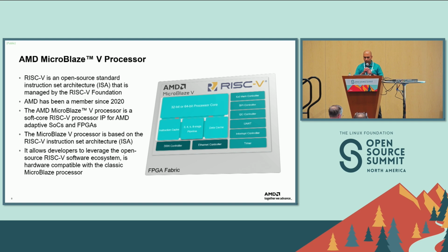So I'm going to talk about the MicroBlaze-V hardware a little bit here. MicroBlaze-V is a RISC-V version of the AMD MicroBlaze soft processor. It is available in most of the AMD devices supported by Vivado, and you don't need additional licensing for MicroBlaze-V. The MicroBlaze-V instruction execution is pipelined, so it can be fetch, decode, execute, memory access, and write back. Such MicroBlaze RISC-V pipeline staging can be done using the Vivado tools.